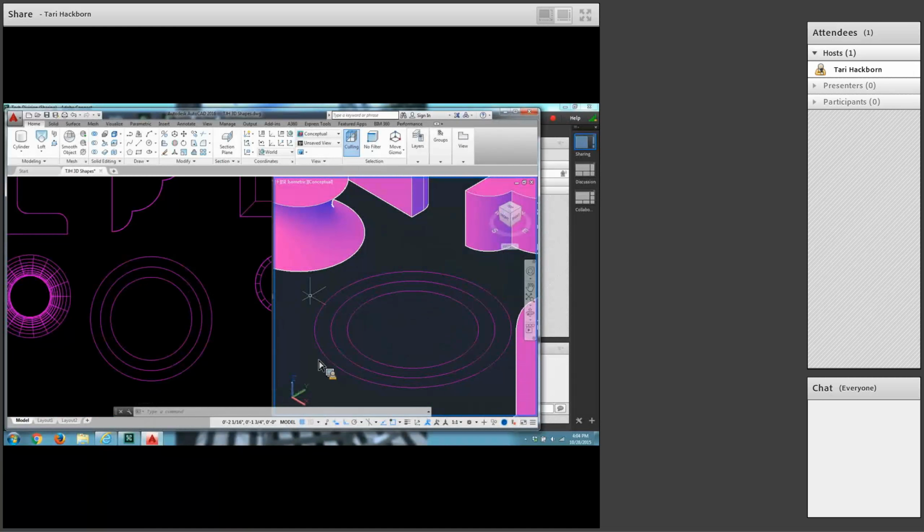That was the smallest one, and it's going up 1/8 of an inch. Move the 1/2 inch. Grab a base point @0,0,1/8, enter. Okay, that's all higher, it went up. Move the 5/8 inch circle a 1/2 inch up.